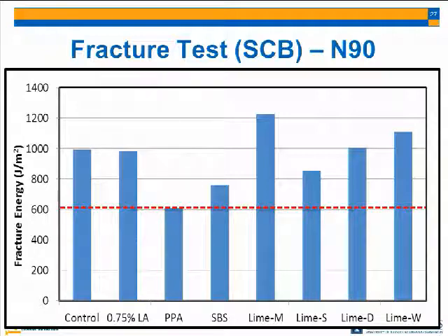You have different binder content for two different mixes. Yeah, for instance. I mean, I'm talking about each mix alone. Yeah. When comparing those additives and modifiers for each mix, the binder content is the same, the aggregate structure is the same, so that we can capture the effect of those additives and modifiers for the case of N70 alone and for the case of N90 alone.